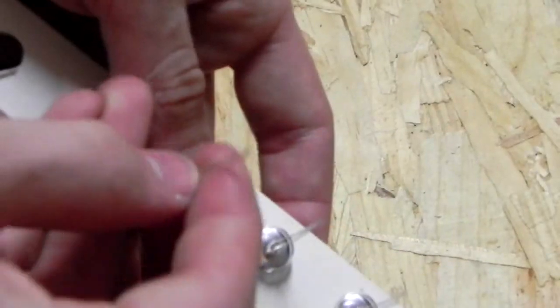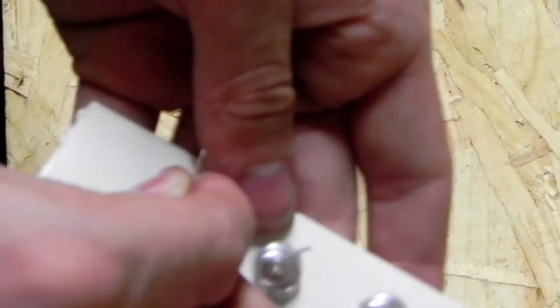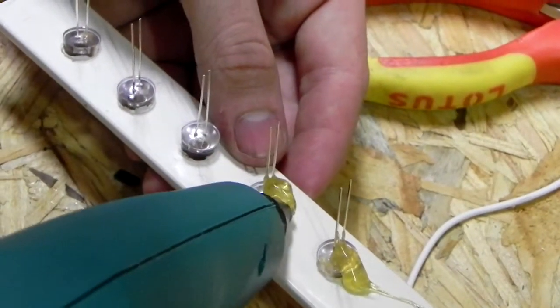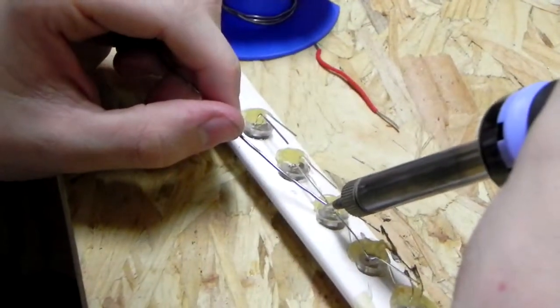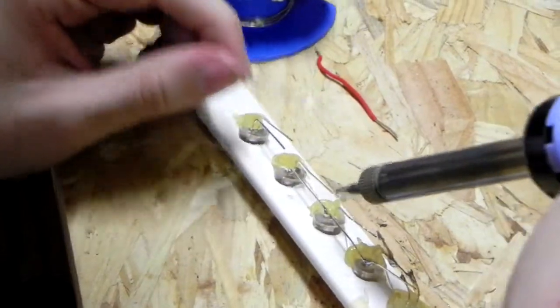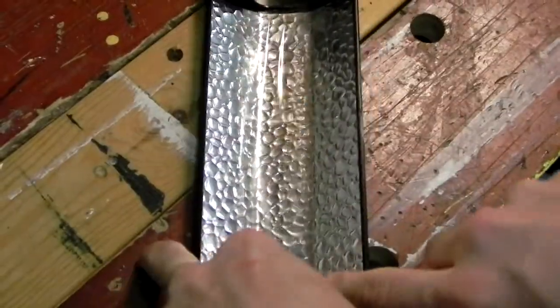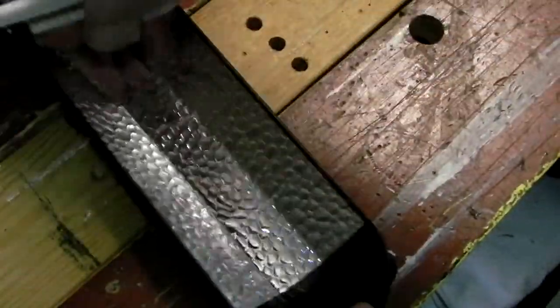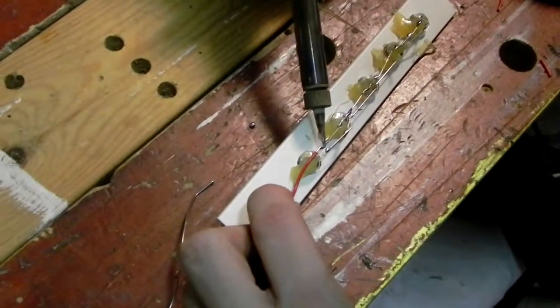I used 5 10mm super bright LEDs, which I hot glued in place on a piece of plastic I just had laying around, and connected them all in parallel. The reflecting material on the back is also a conductor, so to prevent any short circuit with that, I just covered it up with some tape. I soldered some wires to the LEDs and glued the LED strip into place.